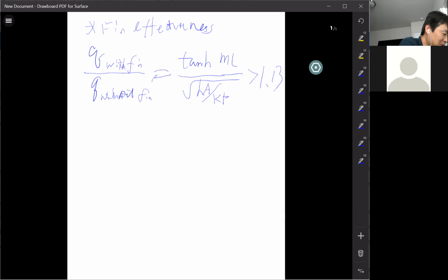It's possible, I'm telling you, because by adding a fin, you really alter the flow. You might decrease the flow significantly. The flow is good for heat transfer, convection, right? You need a stronger flow. So it's even possible that you decrease the heat transfer with your design. So it's important to check those things. Effectiveness is one thing.